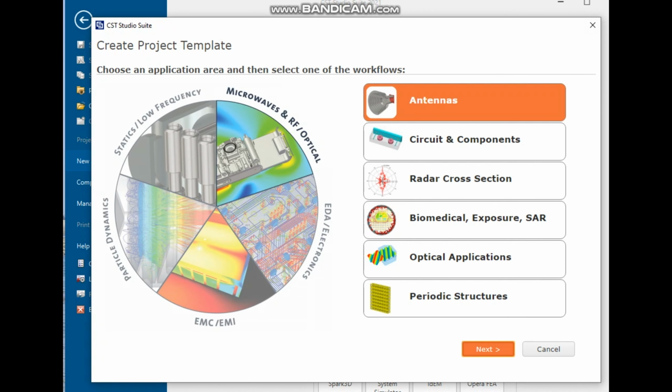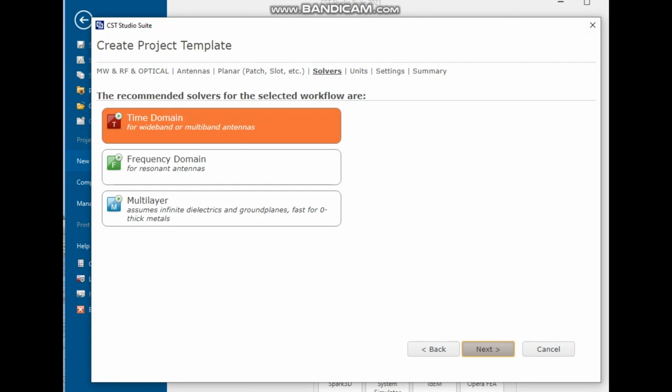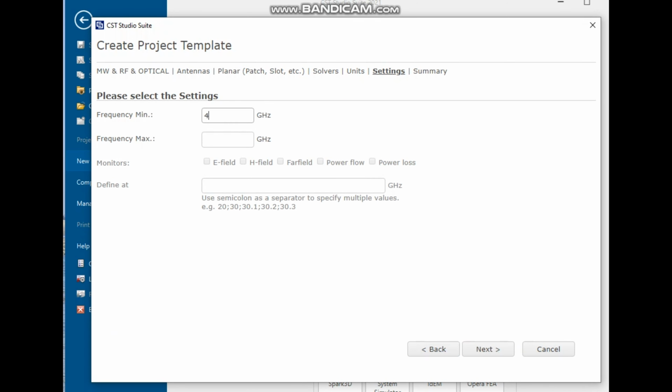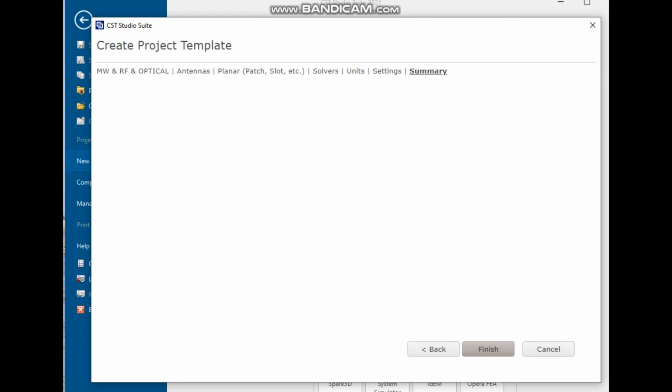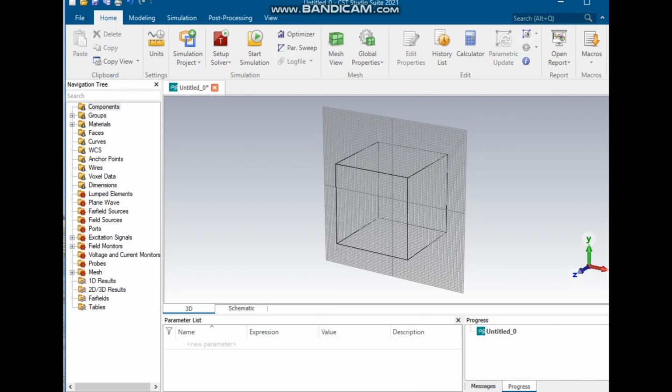We want to design a reconfigurable microstrip patch antenna by using CST. Today we will start. Basically, we set the default frequency range of 1.5 to 4.5 GHz, and we select the E field, H field, and far field, and we click next.